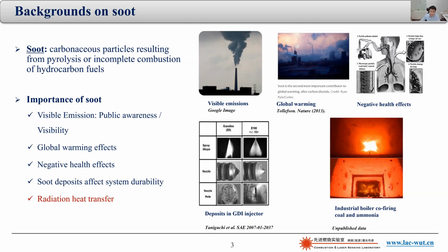We actually meet these problems, and we need to find some solutions to enhance the heat transfer or to change the boiler structures. So this is a very interesting point. But all of this just says that there is a need to actively control soot formation. A prerequisite to do that is that we have to understand soot formation very well. But unfortunately, soot formation has proven to be extremely complex. It includes complex interactions of a lot of sub-processes. For example, you have fuel pyrolysis, precursor formation, soot inception, growth, oxidation, agglomeration, and a lot of that.